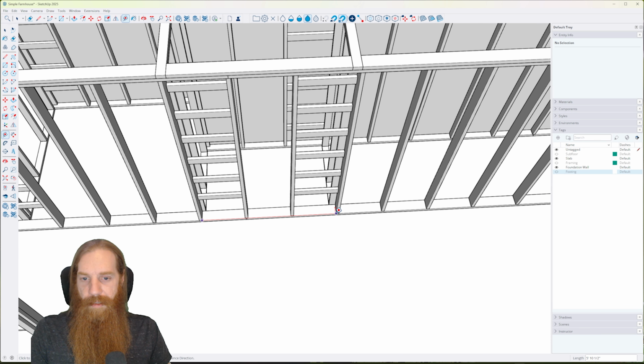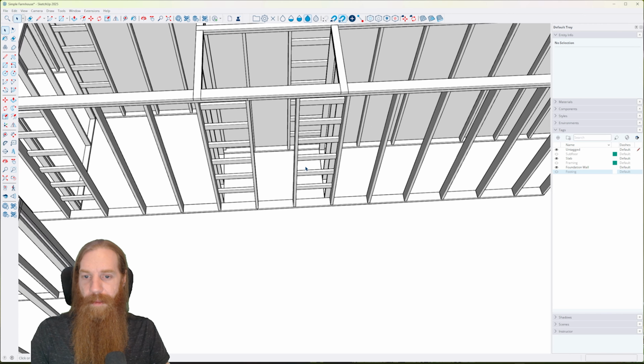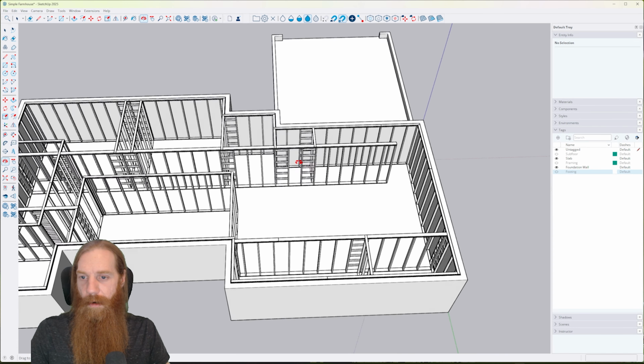Let's say 10 inches off each side or whatever. Maybe 9 inches, because you need to have your rough opening 2 inches wider than what your door size will be. So we will end up shrinking these blocks down to fit that doorway in there.